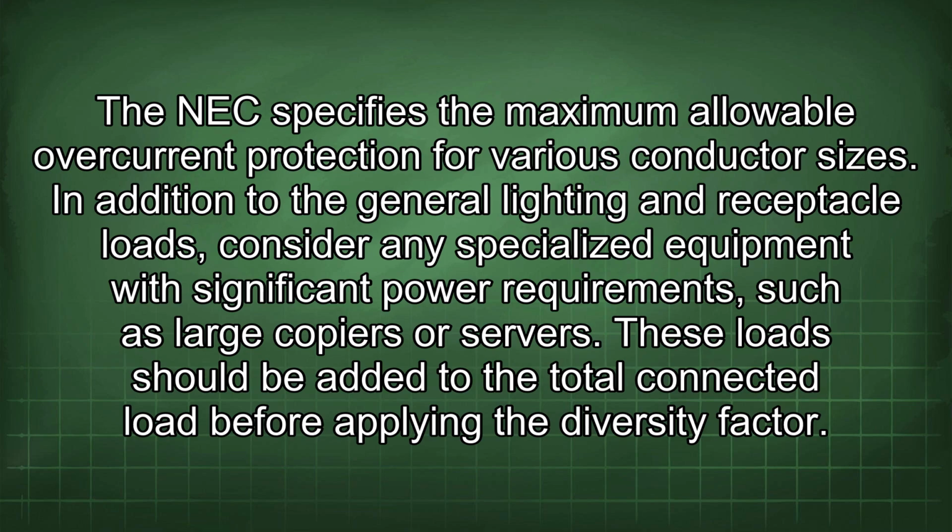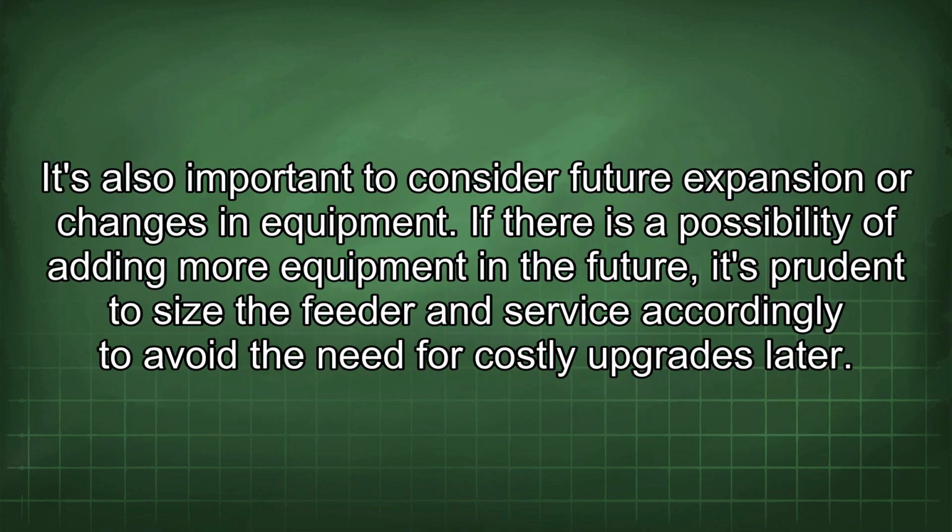In addition to the general lighting and receptacle loads, consider any specialized equipment with significant power requirements, such as large copiers or servers. These loads should be added to the total connected load before applying the diversity factor. It's also important to consider future expansion or changes in equipment. If there is a possibility of adding more equipment in the future, it's prudent to size the feeder and service accordingly to avoid the need for costly upgrades later.